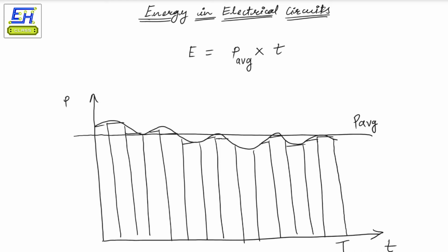And most of the time manufacturers will give you this average power consumed. Let's say if that is a kilowatt, this means that your refrigerator will consume 1 kilowatt in 1 hour. Or if we were to rephrase, this means that if you were to assign a single value, the power consumed will be 1 kilowatt at every instant. So we are assuming that at every point in time between this 1 hour of observation window, this thing will consume 1 kilowatt. But the drawback of this average power method is that you will not get accurate measurements.